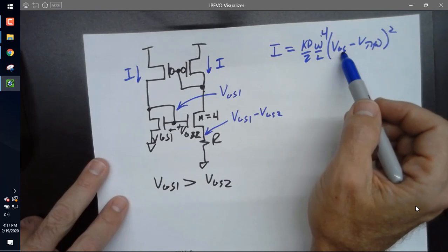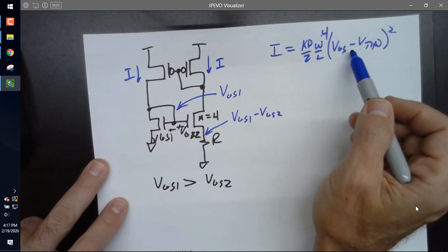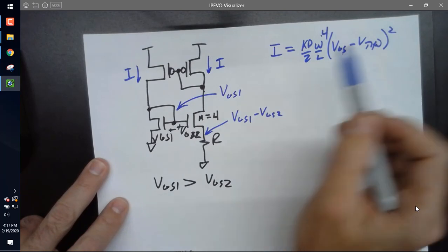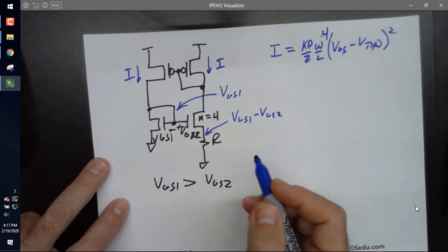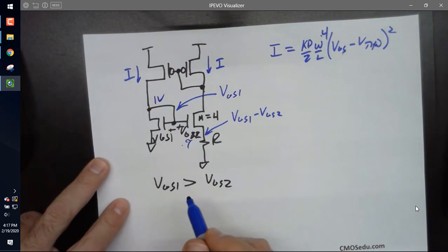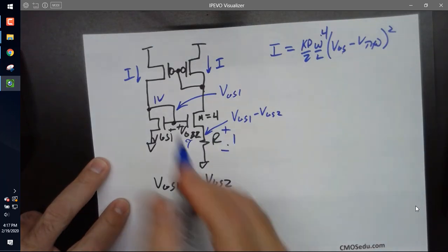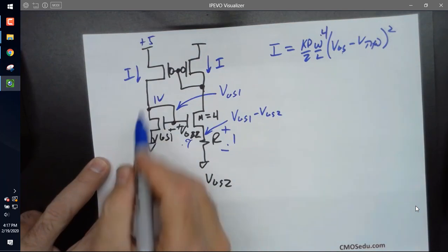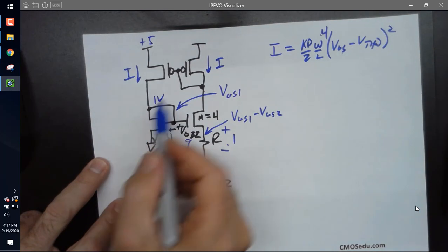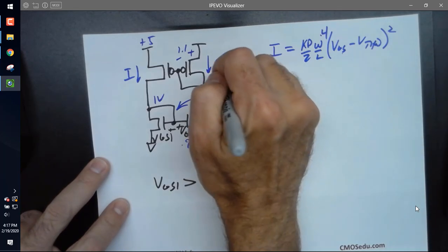My question is, if you connect any side over here, the left circuit, would that be pulling VDD to ground? No, because let's just put some numbers in. Let's say VGS is 1, and this voltage is 0.9. Okay? So that means there's 0.1 volts across here, right? Let's say this is 5. Well, this is still 1. Let's say the VSG is 1.1, so that this is 3.9.